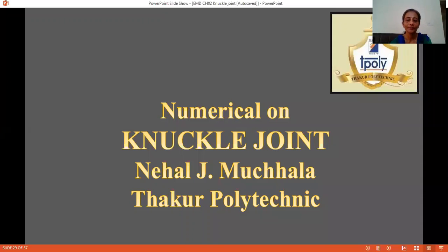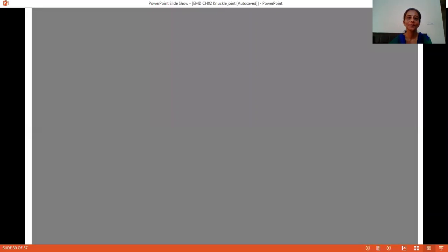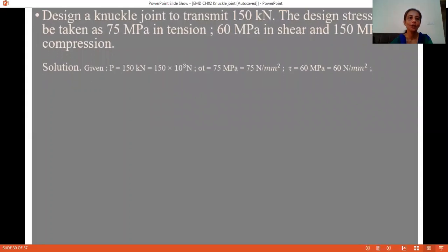Hello students, today I will explain one problem on design of knuckle joint. So here is the question. Design a knuckle joint to transmit 150 kilonewton. Design stresses are taken as 75 megapascal in tension, 60 megapascal in shear and 150 megapascal in compression. So first of all, we will write the given data.